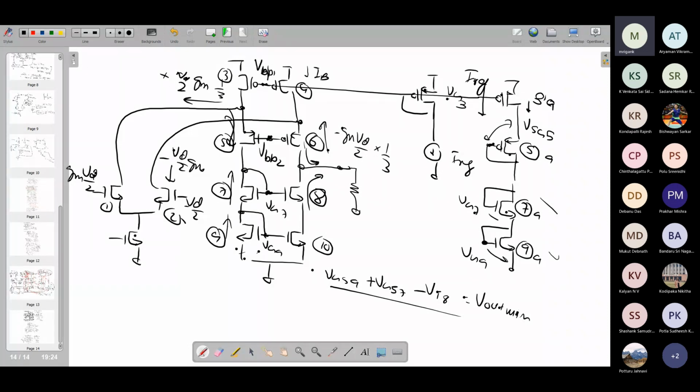And you can also go for reduced cascode swing. We have discussed it earlier. Probably for today we are getting late, but at least the simple biasing with the normal cascode mirror should be clear enough. Then I can give you some simulation exercise where you can connect these and see how the VGS are developed, and